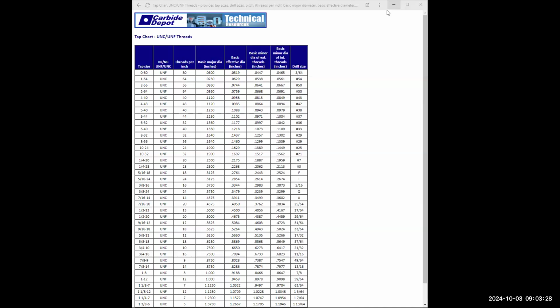Now, do me a favor. Type in the word snap angle. Snapang, S-N-A-P-A-N-G. Enter. And I want you to type in the angle of 41, which is half of the 82. Enter. All right, then I want you to come here, type in L for line, enter, click here, and look. Drag a line, click, enter.